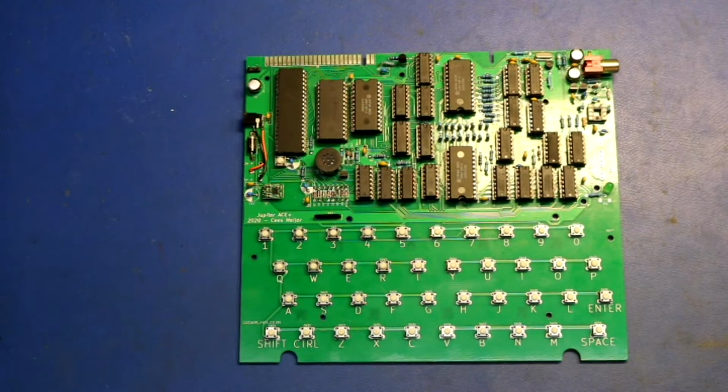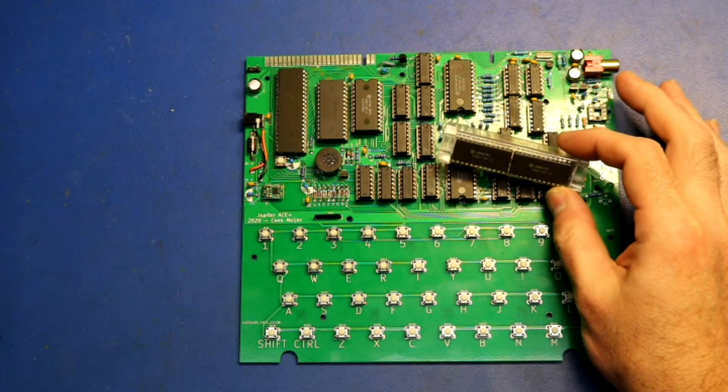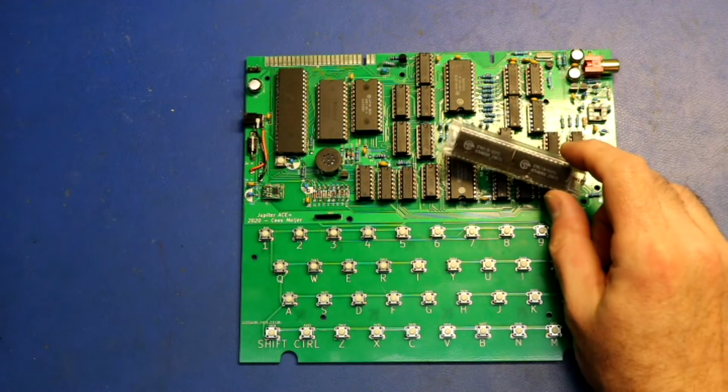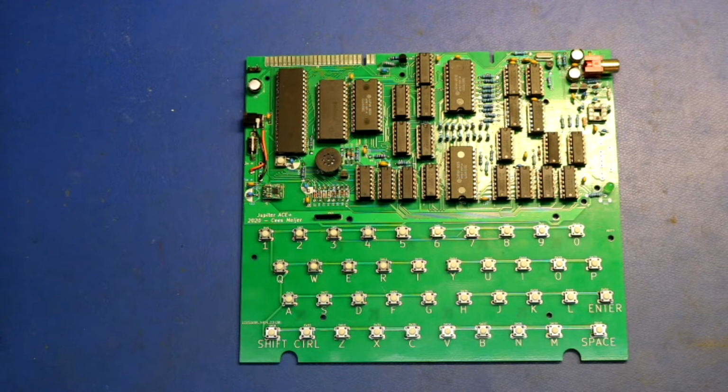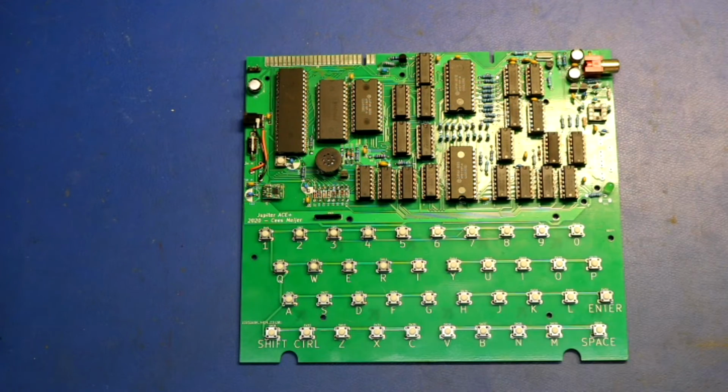Okay, so I tried a couple things to fix the character generator RAM corruption issue. The first thing I tried was switching the RAM chips. The ones I had were 400 nanosecond. I got some 200 nanosecond and some 55 nanosecond, both from JDR Micro Devices on eBay, and I replaced the video RAM and the character generator RAM. That didn't improve it. It behaved differently, but it did not behave correctly.